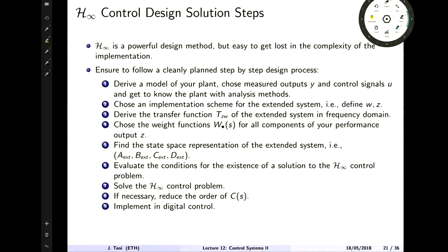There you also have difficulties because you solve optimization problems during the execution of your system, and you have to make sure that these always have a solution, they shouldn't be infeasible, and there's a lot of steps to take there. It's also quite complex. With H infinity, you have the advantage that you are still in frequency space, so you still have a frequency space representation of the controller, which gives you some other methods of understanding that maybe are not as easily available in other methods.